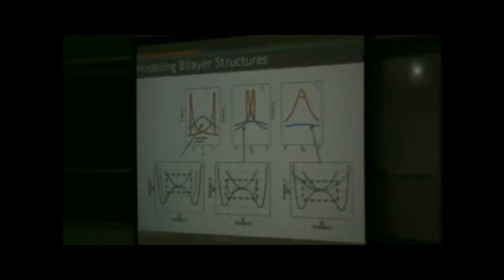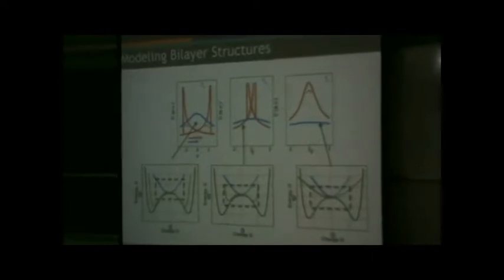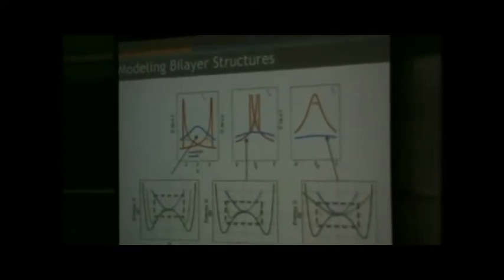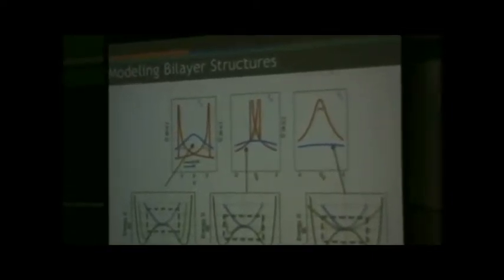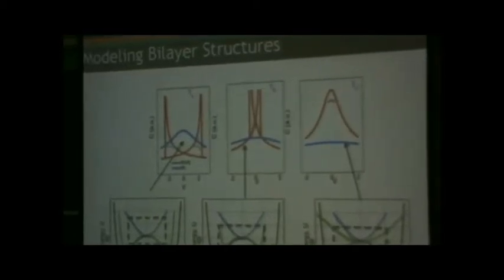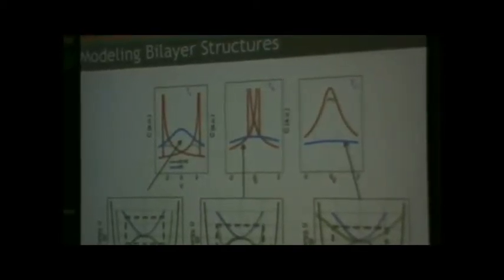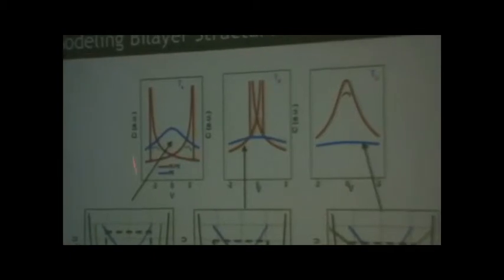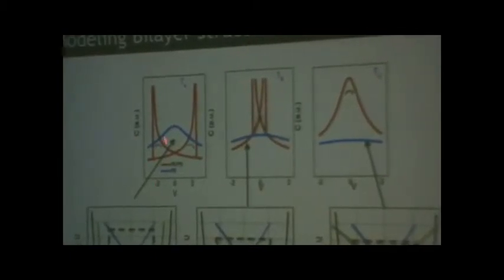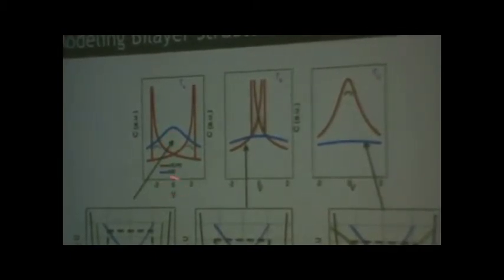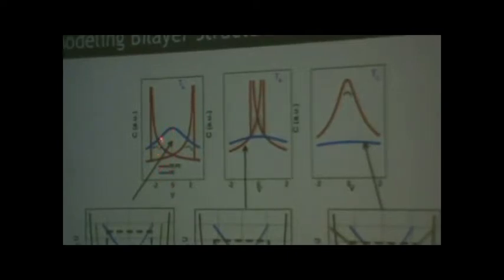Let's say I take a paraelectric and measure CV theoretically, and then I put some ferroelectric on top of the paraelectric and again measure CV, and I compare them. If I look around zero voltage, I see that the paraelectric capacitance is much larger than the heterostructure. So I'm not seeing any negative capacitance.